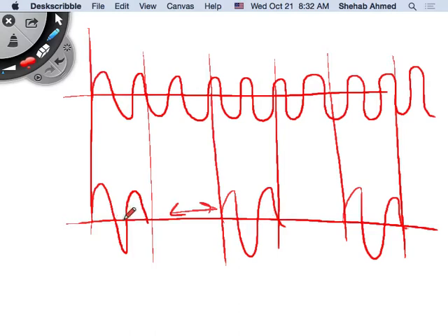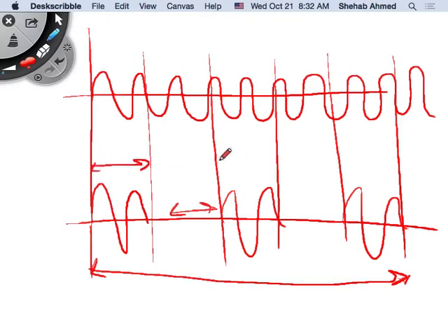If I calculate the RMS value, I have to look at my period. My period now is this, right? This is my full period. In this period, I am connecting for a while, disconnecting for a while, connecting for a while, disconnecting for a while. What did I do? I change the RMS value as well, right? So I can change the RMS value this way as well, yeah. So this is called integral cycle control. The other is called phase control.